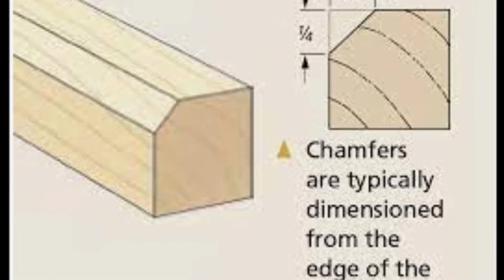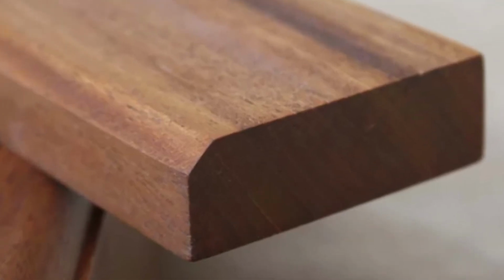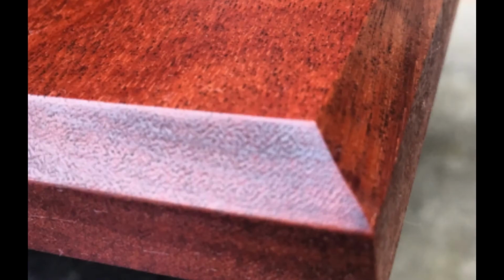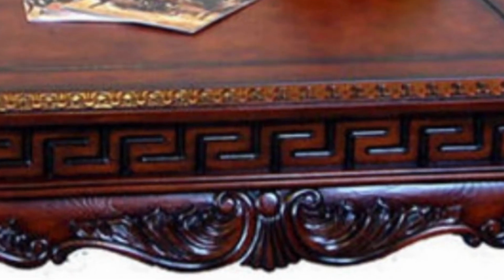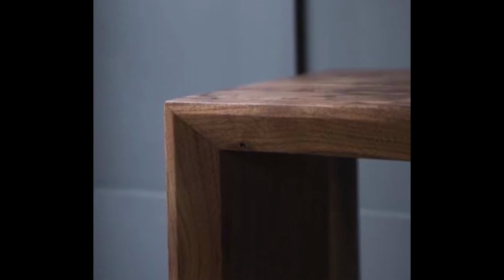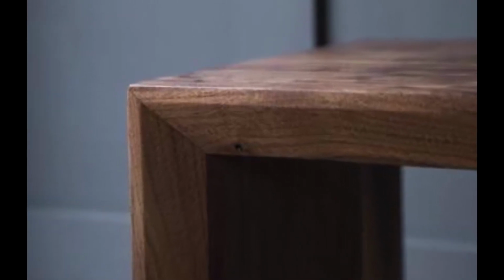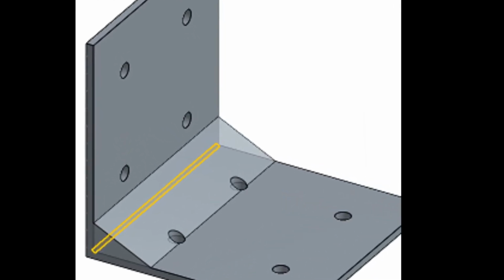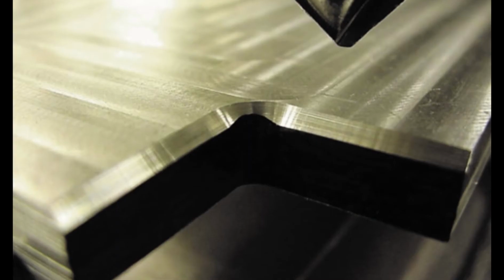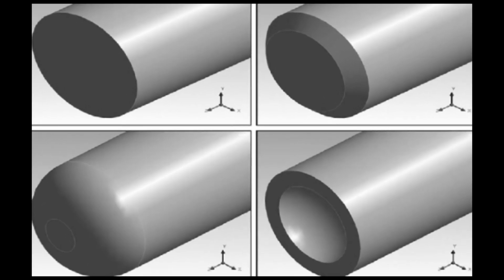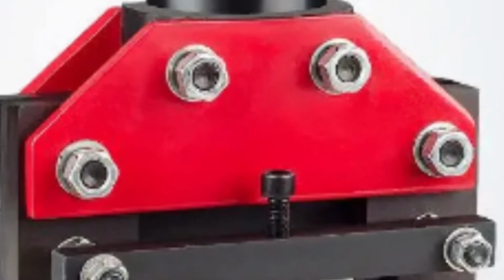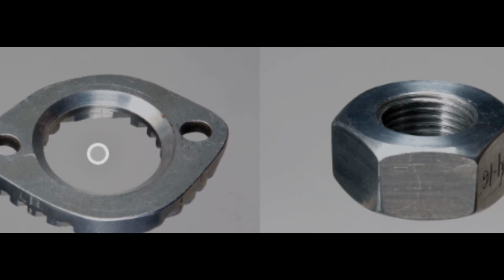The chamfer creates a beveled corner. You may have seen a chamfer in a building corner, machine or some normal drawing. Fillet and chamfer go hand in hand. A chamfer can be given along an edge of a surface or a corner. Chamfers are used in furniture, counters and tables, and also in mechanical equipment. This is done to ease the edges, and it also protects the user from being hurt by the sharp edge. And also it enhances the finish of the object and reacts very well to the light around.